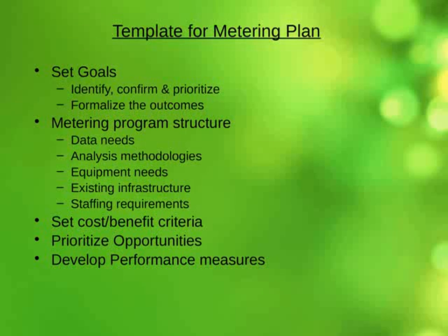In terms of the metering program structure, again, you're going to want to look at what kind of data you're going to extract, whether it's power quality data or basic voltage, current, and power, the equipment needs associated with putting that metering into place, and what you have as existing infrastructure.